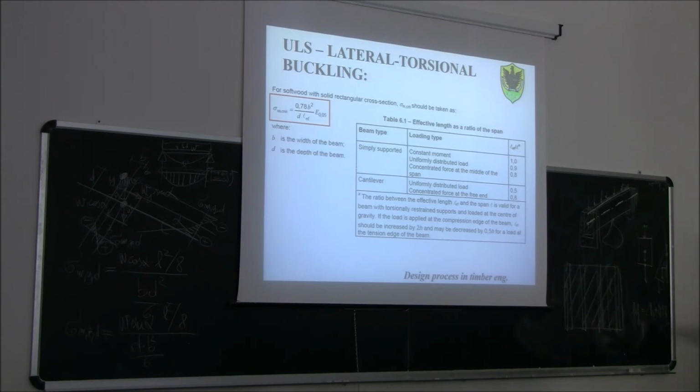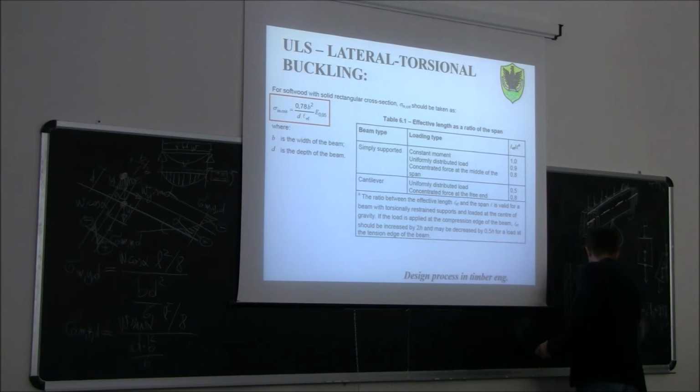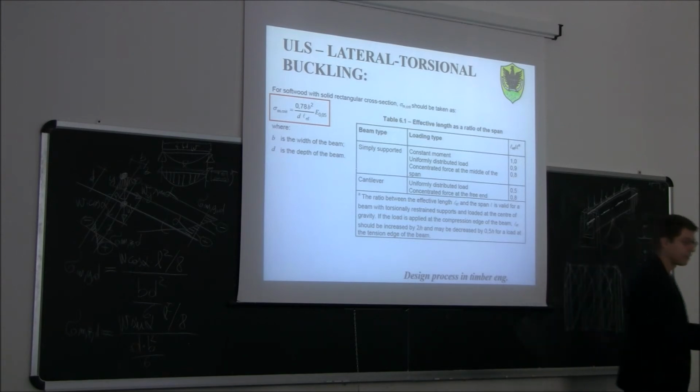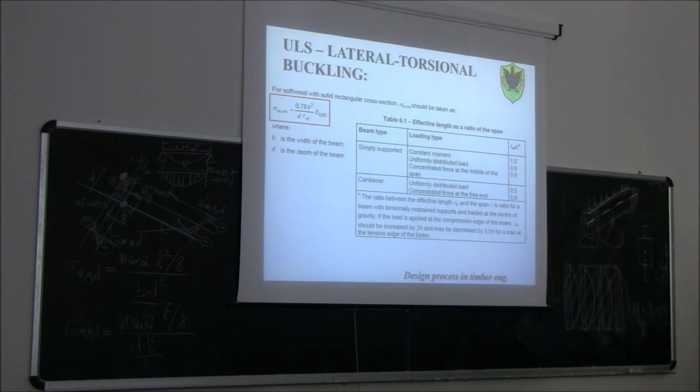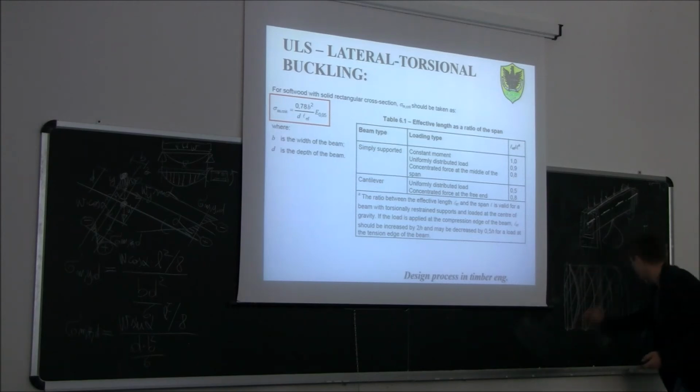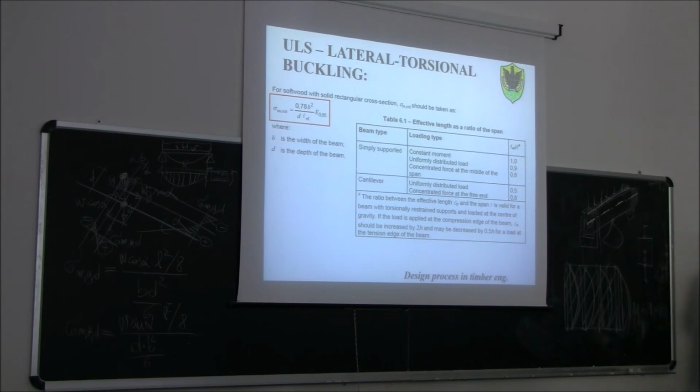To buckle in this way, first of all all of them should buckle. But then you see this rectangular floor should distort, should become a floor like this. So the concrete slab should in some way fail, which is not possible, because the concrete slab is stiff in its plane.